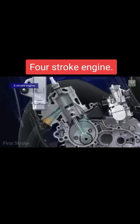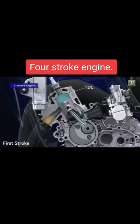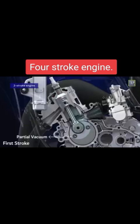In the first stroke, the piston is at its bottom dead center position. During this stroke, the piston moves upwards from bottom dead center to top dead center. It closes the transfer port and the exhaust port. The charge of air and petrol mixture, which is already there in the cylinder, is compressed. Due to the upward movement of the piston, a partial vacuum is created in the crankcase and a fresh charge is drawn into the crankcase through the uncovered inlet port. At the end of this stroke, the piston reaches the top dead center position.